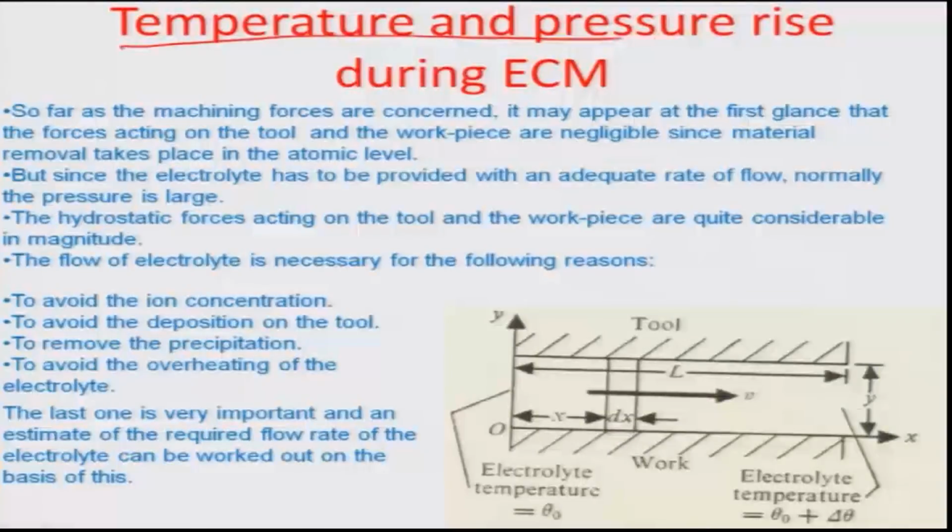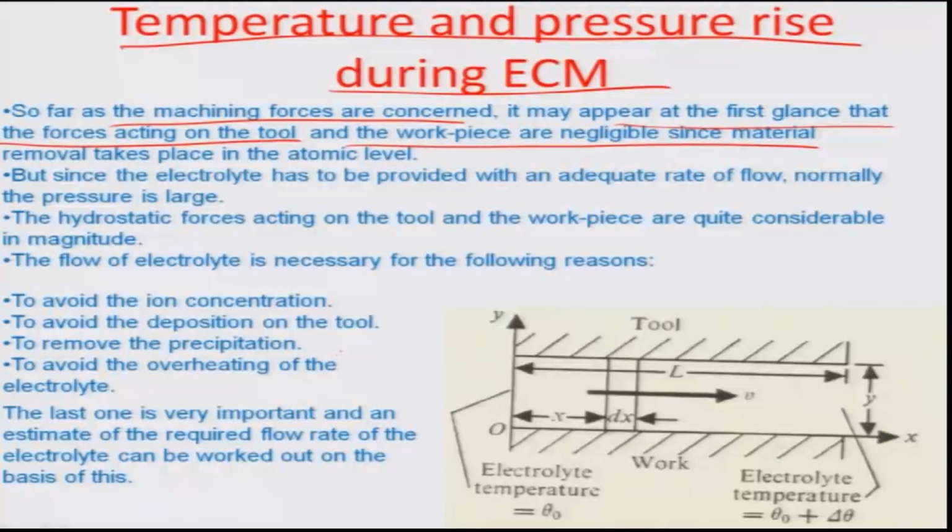So, let us look at the temperature and pressure during ECM, and we will just simply use a one-dimensional problem here. So far as the machining forces are concerned, it may appear at first glance that forces acting on the tool and the workpiece are negligible, since material removal takes place at atomic level. But since the electrolyte has to be provided with an adequate rate of flow, normally the pressure is large. So, this is something that we must understand.